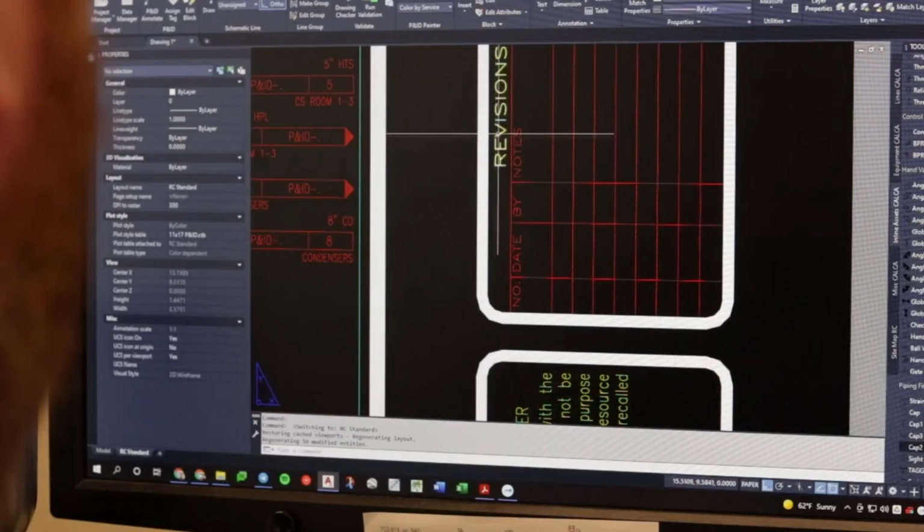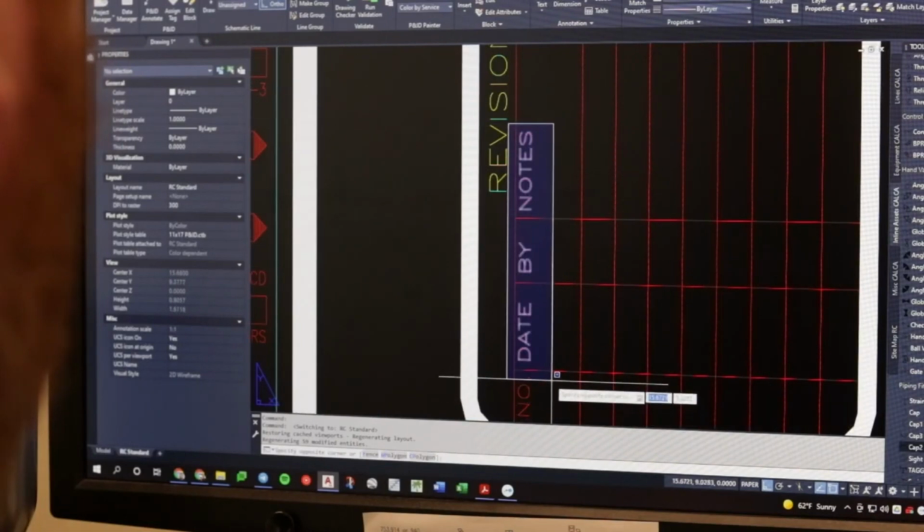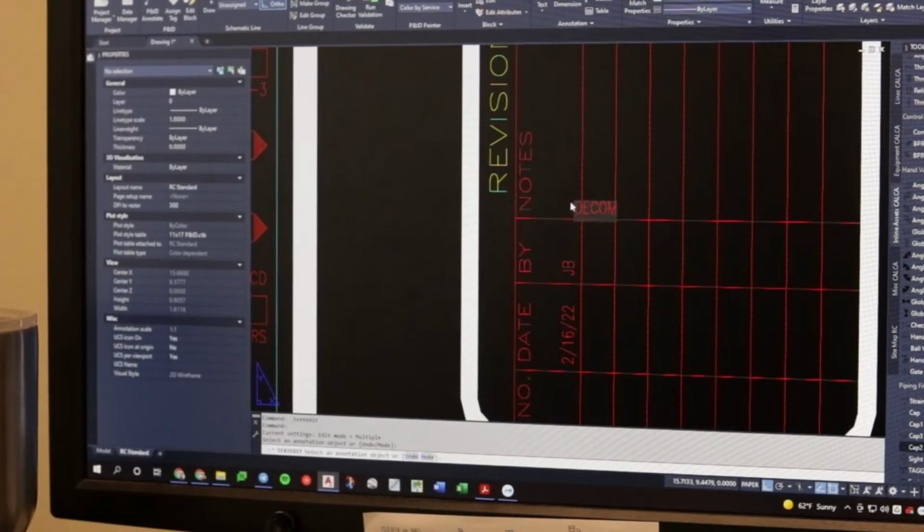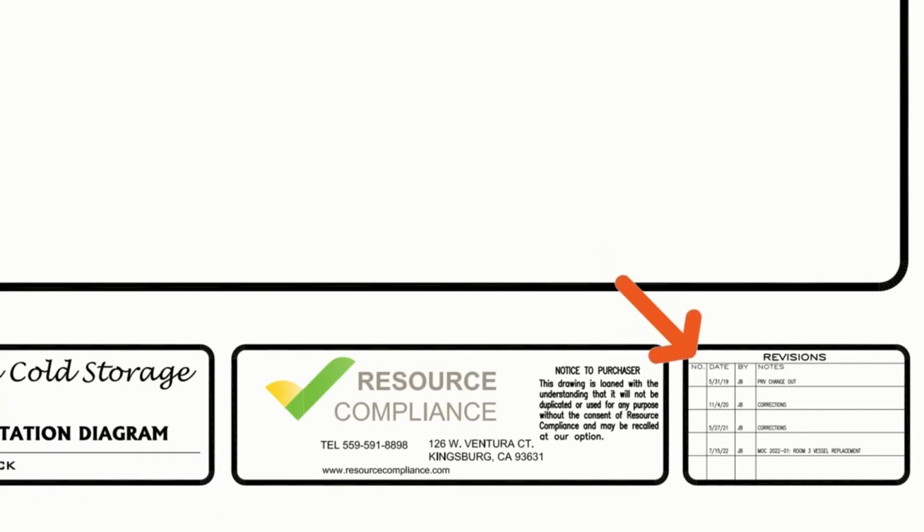As with other requirements, the mantra, "if it isn't documented, it didn't happen," applies to P&IDs. With that in mind, make sure that all P&ID modifications are recorded. A common way to capture P&ID changes is by including a revision history section on each page of a P&ID title block.